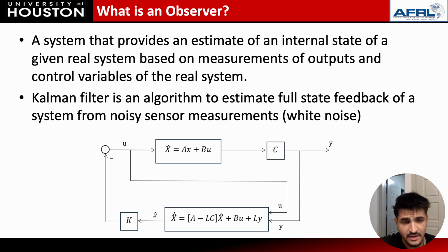For our system, again, since it is going to be an LQE, LQR system to make an LQG, the LQE is a Kalman filter specifically, where it's estimated full state feedback of the system from noisy sensor measurements. So we're also going to be injecting white noise into the system, so that the Kalman filter can act as a filter for it, and still gives the estimates with the LQR being gain scheduled.